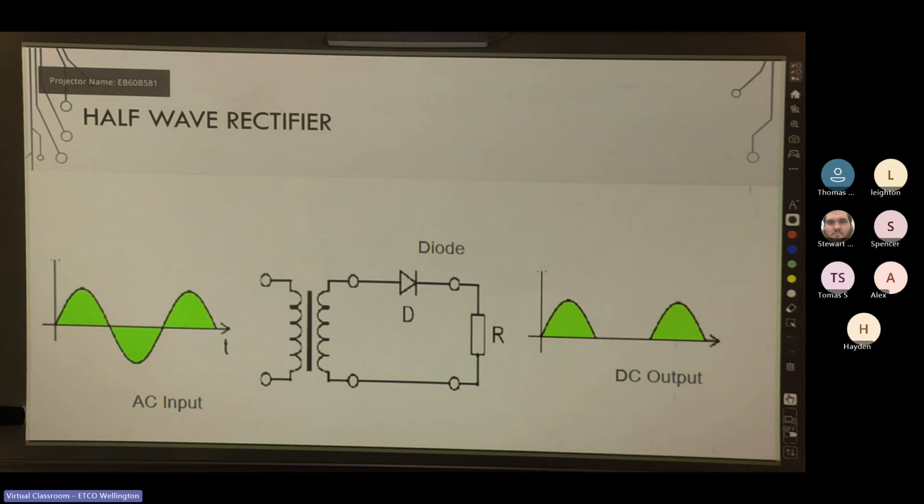Cool. So this is an example of a half wave rectifier. Basically it has a diode on one arm, so it will only rectify half of the AC waveform. It wastes half of the AC wave as it only conducts half the cycle. The output is extremely lumpy and in most cases must be filtered with capacitors before use. It's obviously not very useful, a waste of power, power wasted to heat. It's the most simple form of rectifier from AC to DC.